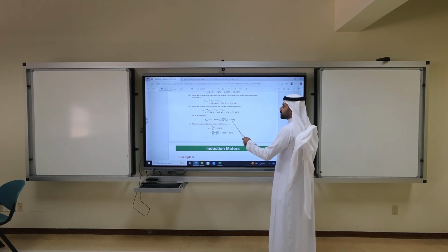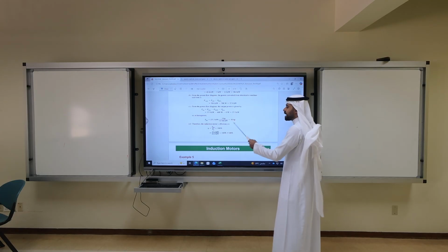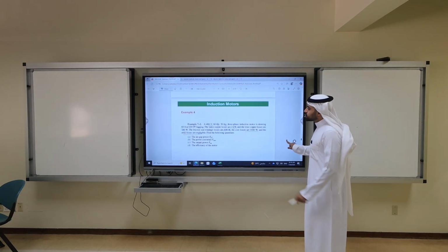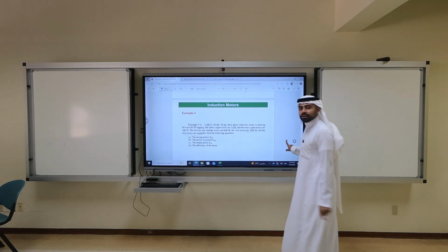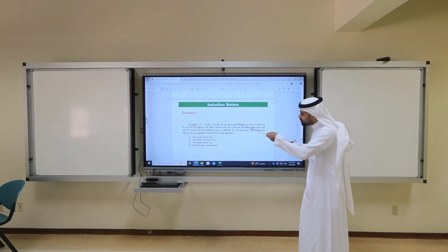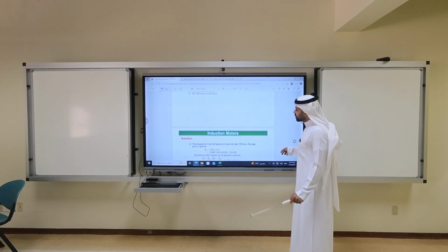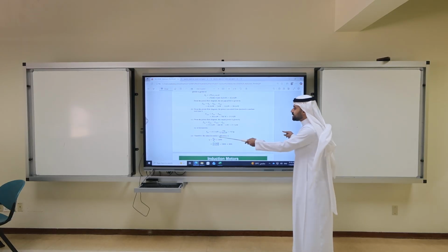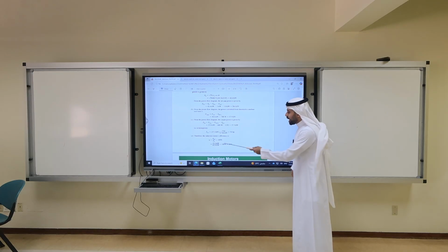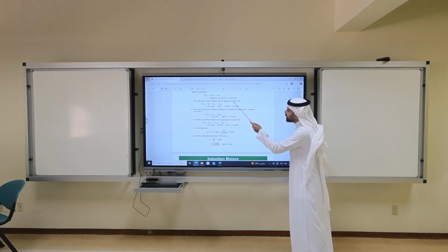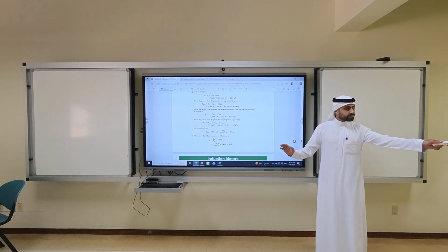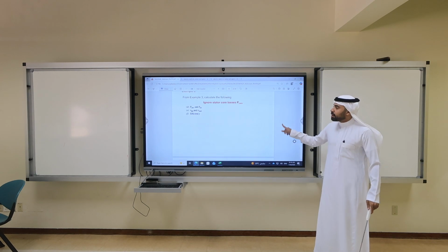Then here is a step, he converted it to 50 horsepower. Am I getting 50 horsepower? Yes, that's from the problem also, a quality check. Check that the output power should always match the horsepower given. What is the efficiency? Output power over input power times 100, output 37.3 and input 42.4. And this problem is solved. Easy? Easy. Let's go to the harder problem.